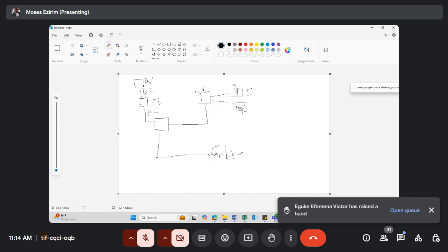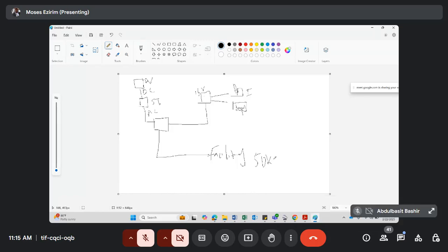So now let me assume that the load in this facility is 50 kilowatts, or let me say the energy that I need is in kilowatt hours. And the energy that is coming from the PV is 70. What will happen? Out of this 70, 50 kilowatt hour energy will power this facility. Then the remaining energy will pass through this output. Remember, I mentioned that this output is bidirectional. We pass through this output and charge the battery. The remaining 20 kilowatt will charge the battery.